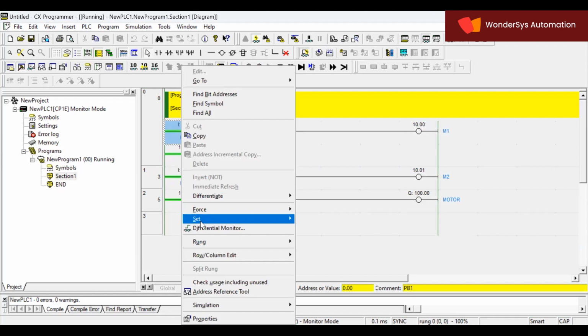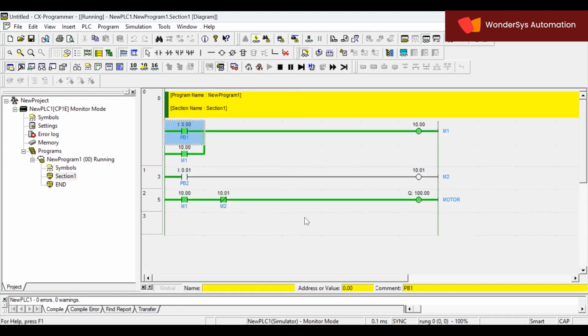Now, let me switch on this one. So now I have switched it on, okay? So this memory address, what is there? You can't see it physically, okay? It is internally stored, the 10.0 and 10.1. Now don't look at this last rung. What I have done is I am storing this input condition in the memory 10.0 continuously through latching, okay?